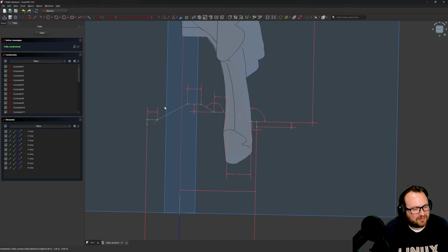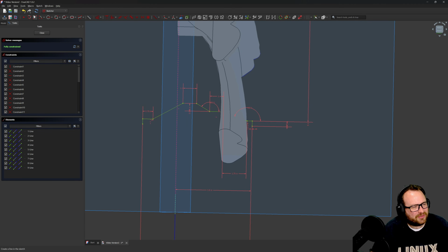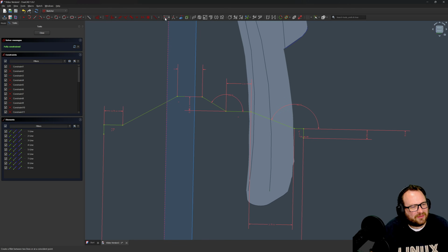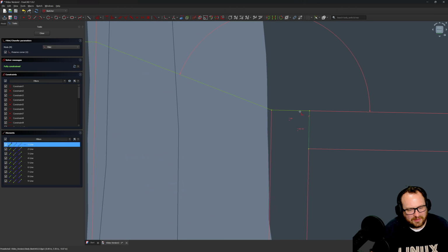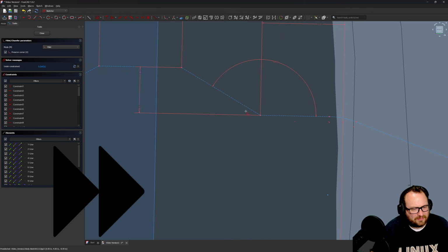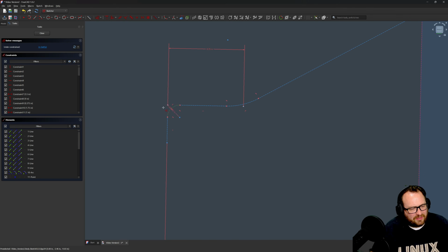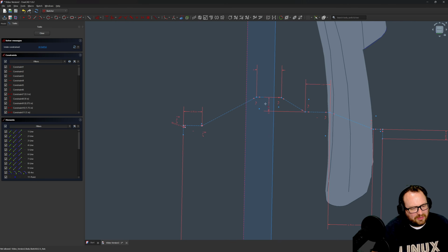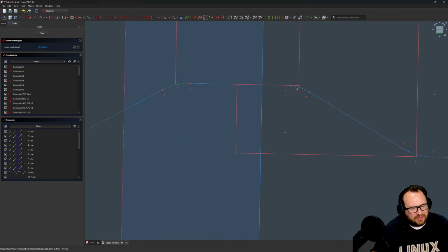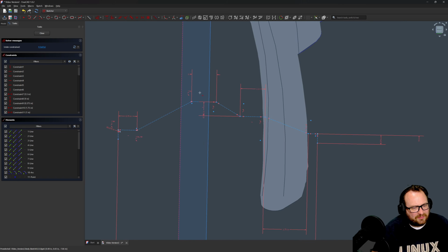We'll go with making all of this for construction. And then I'm also going to trim my view here. We'll add some sketch fillets. All right, we'll keep these pretty modest. And we're going to say this will be 0.075. We're going to hit E for equal and get all of these at the same radius. Wow, I'm having a hard time clicking. So get these all at the same radius here.